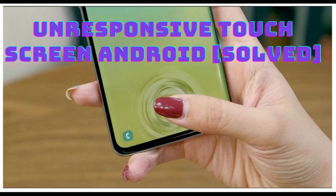Surface acoustic wave (SAW) technology uses ultrasonic waves that pass over the touchscreen panel. When the panel is touched, a portion of the wave is absorbed. The change in the ultrasonic wave registers the position of the touch event and sends this information to the controller for processing. Surface acoustic wave touchscreen panels are the most advanced of the three types, but outside elements can damage them.